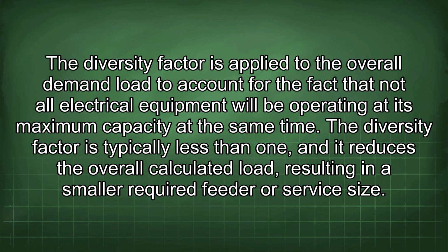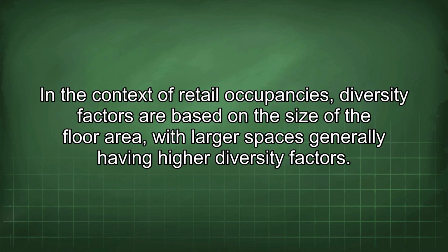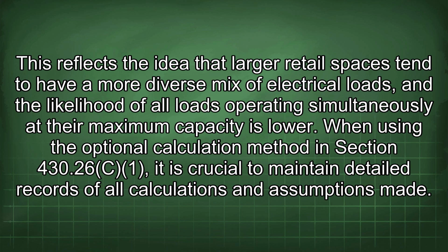The diversity factor is applied to the overall demand load to account for the fact that not all electrical equipment will be operating at its maximum capacity at the same time. The diversity factor is typically less than 1, and it reduces the overall calculated load, resulting in a smaller required feeder or service size. In the context of retail occupancies, diversity factors are based on the size of the floor area, with larger spaces generally having higher diversity factors. This reflects the idea that larger retail spaces tend to have a more diverse mix of electrical loads, and the likelihood of all loads operating simultaneously at their maximum capacity is lower.